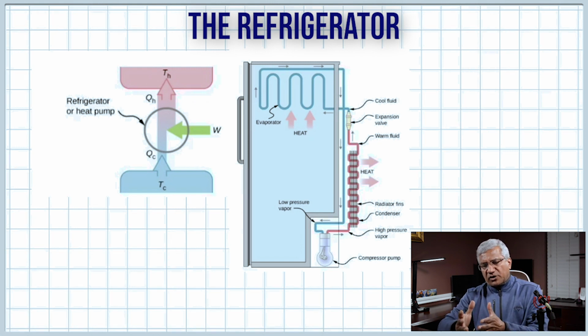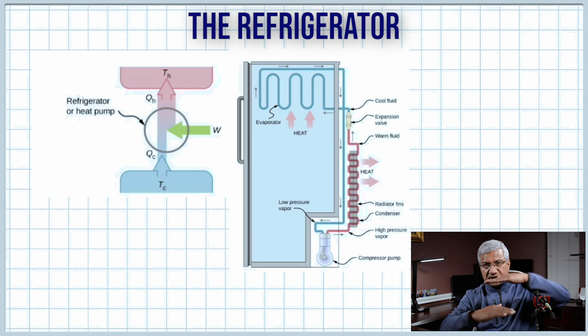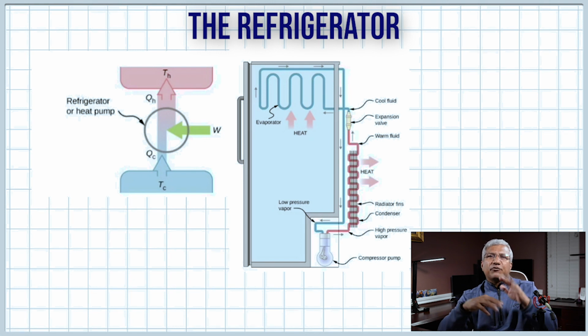And when you actually look at a functioning refrigerator, on the right side, we see a compressor with the working substance, which in this case would be Freon. So as the piston comes down, work is done on the working substance, so heat is produced, number one, and number two, Freon gas now becomes a liquid because of the high pressure.